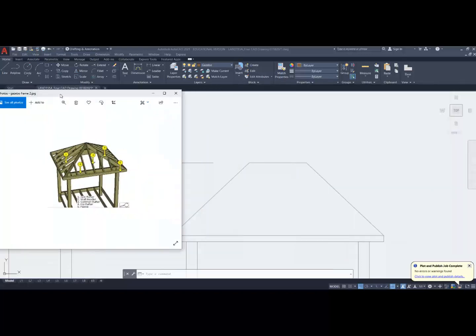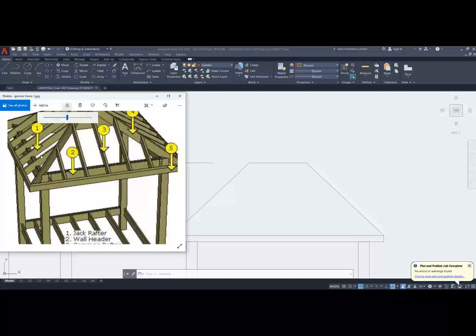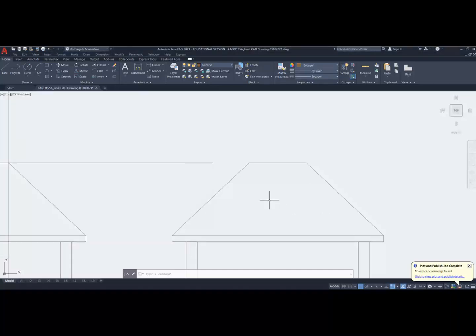Now here's the diagram I've got here that shows sort of the fascia, the joist coming down on top of the beam. Notice how the joist, this is a good drawing in this regard. I'm just going to zoom in on it. The joists are notched out to sit on top of the beam, and then they come down and they support the fascia board. Now, it's a good overall drawing. It doesn't get into the specifics, but this is essentially what we're going to be drawing as we work through this project here.